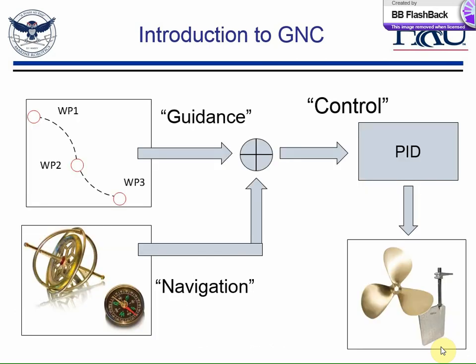So in this slide, I just have a pretty quick summation of what you would do in a maritime environment. You guys know what, on the bottom left-hand corner, what those are? So we got two sensors. What are those? Compass, and what's the second one? Gyroscope, right on. So with those, what are we able to measure? Direction. We're able to get our bearing and attitude. Yeah, so it would be our attitude and our angular rates for our body, right? So with the gyroscope, you're typically able to get your z-axis rate. If it's a nicer gyroscope, you're able to get a 3-axis rate for your x, y, and z axis, right?